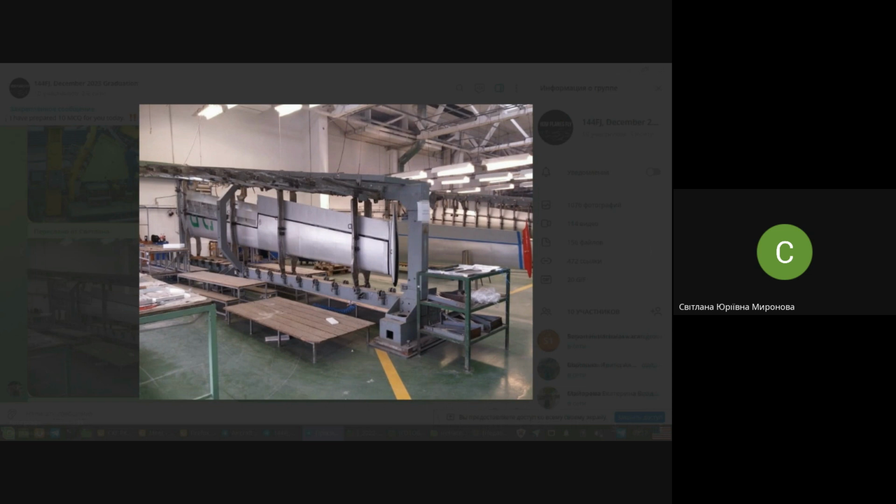Once again, a jig consists of a carcass or skeleton, which may be of different types. Either it's produced in the tool shop completely as a whole piece, and in this case we call it a frame-like skeleton, frame-like carcass of jig. Or another variant, it's produced by pieces, columns separately, beams separately, like we did in our laboratory work about instrumental stand and loft conductor and other elements of the jig.